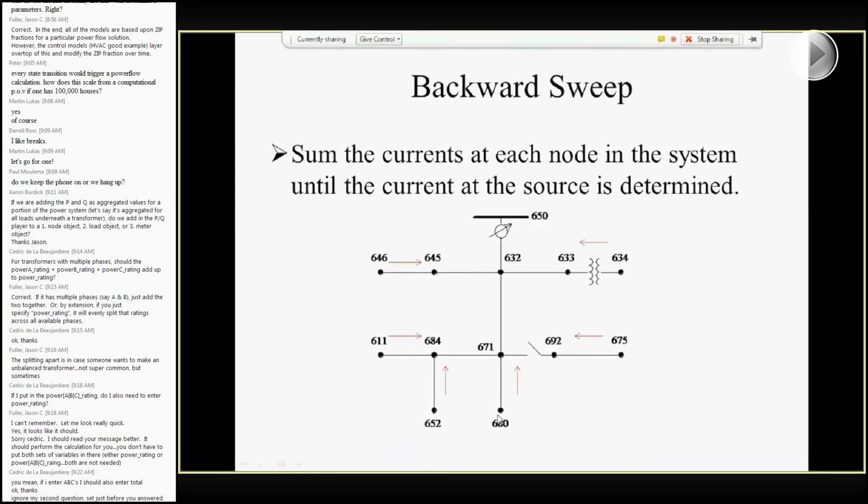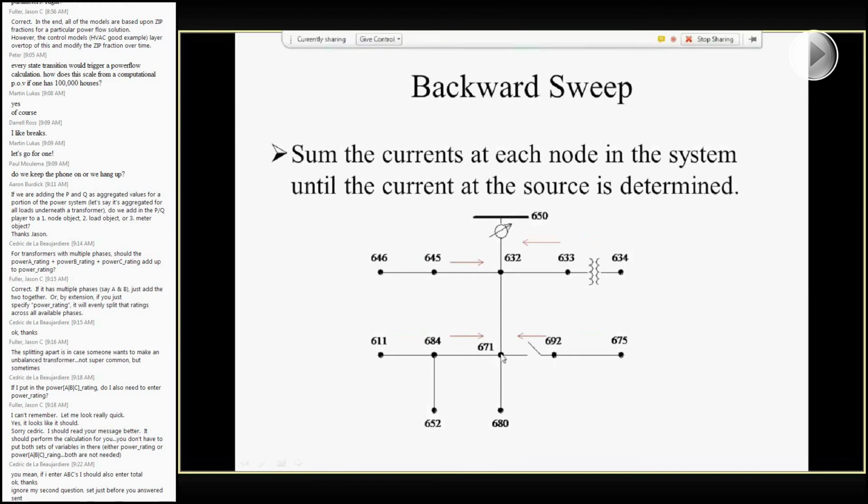So in this particular case, you're going from your end-use devices all the way up to your subtransmission or your feeder node, or head of your feeder. So you start summing these up along the branches. Eventually you'll get to the point where branches converge, so you'll sum all of those, basically like their individual spot loads converging, and add up all their current injections. And you'll do that all the way up to the top of the feeder.